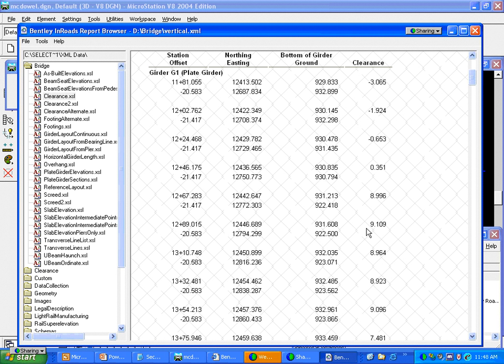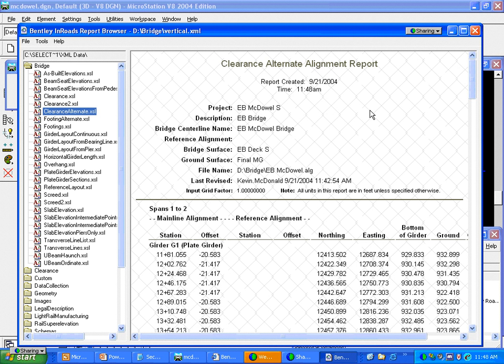And what this does is it goes along the center line of that girder, compares it against the surface representing the bottom of the underneath the bridge, and it compares and gets a clearance along each of those girders. So those 2 exterior girders on my eastbound bridge there are going to be the ones that I'm concerned with. And as you can see, we've created and delivered just a number of clearance reports here. And again, those are customizable for you as you want.